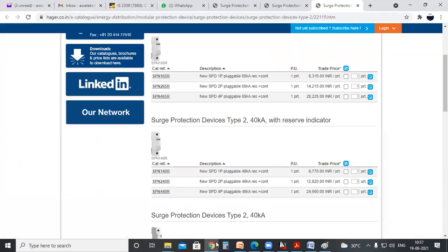Normally this cartridge will be in green color. Whenever a lightning strike happens, the color changes, and the capacity is getting reduced. Whenever the color gets close to the red color value, you have to change the cartridge. You don't need to change the entire device. You can change the individual cartridge based on the colors and the value mentioned. They will also mention the time of change, when we need to change the cartridge.